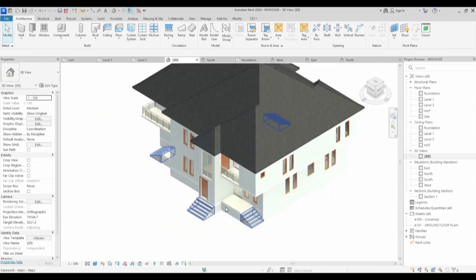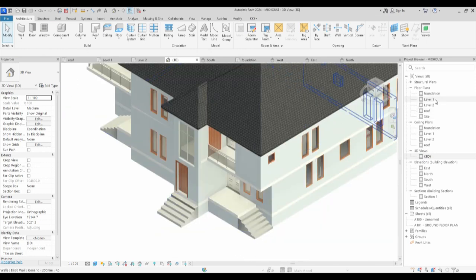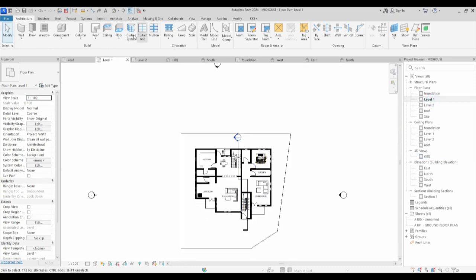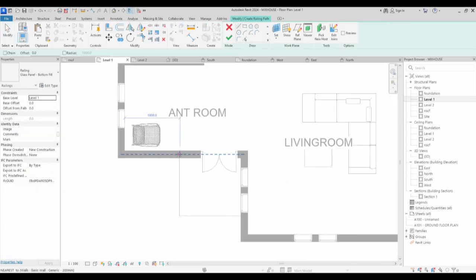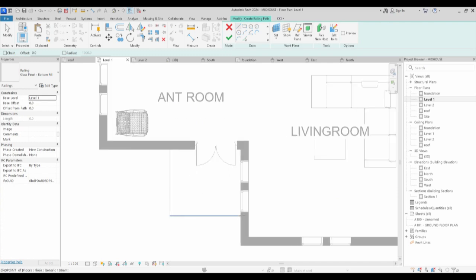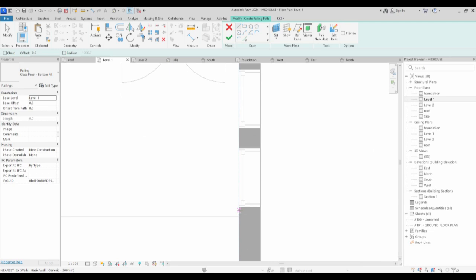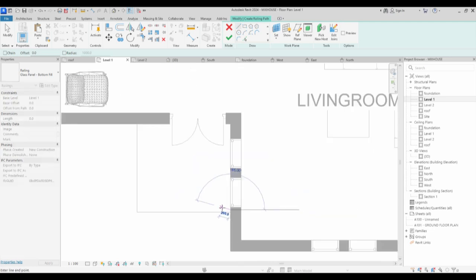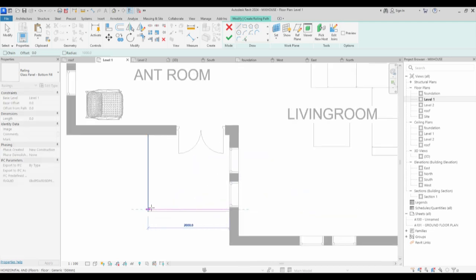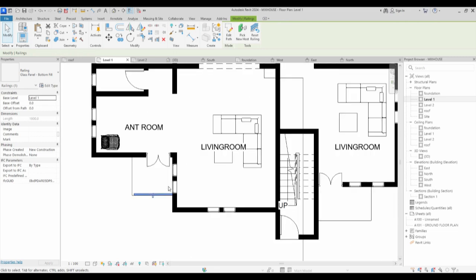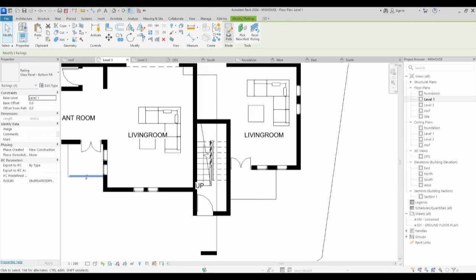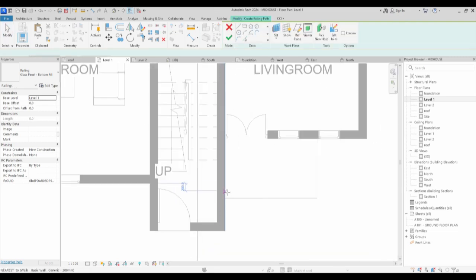So these are taking shape, things are forming. So level 1, 2, I'll click on that and say modify and say railing. So the railing is going to be here, except I change the pattern in which I don't think it's going to be ideal. So railings will be here on this once I enter this side. So the same thing I'm going to do here, create a pattern and then fill the railing here as well.